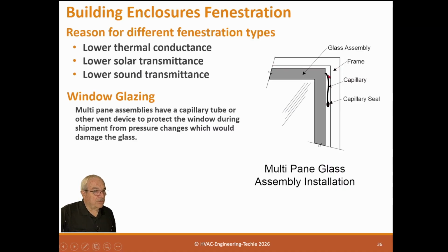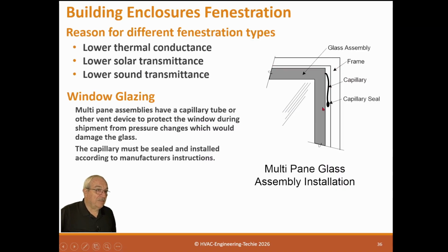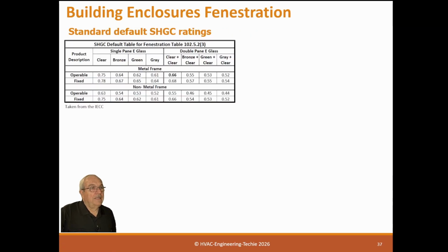And as a commissioner, that's one thing you need to verify, that they've actually sealed up all the glass capillaries. The capillary must be sealed, like I just said, according to the manufacturer's instructions, and normally it's a piece of silicone caulk.